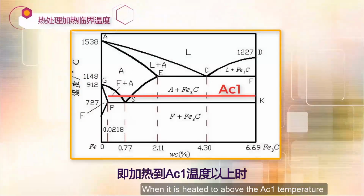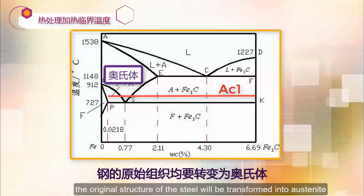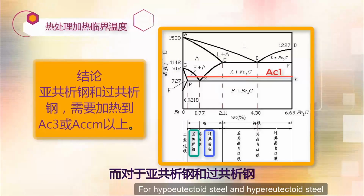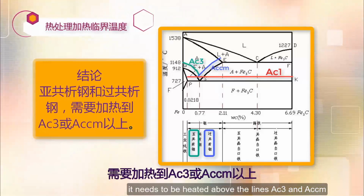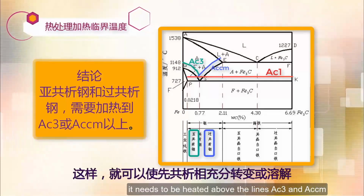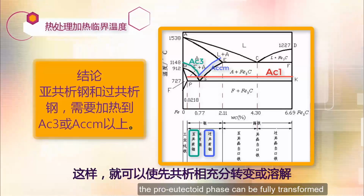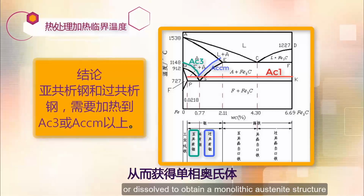When it is heated to above the AC1 temperature, the original structure of the steel will be transformed into austenite. For hypoeutectoid steel and hypereutectoid steel, it needs to be heated above the lines AC3 and ACCM. In this way, the pro-eutectoid phase can be fully transformed or dissolved to obtain a monolithic austenite structure.